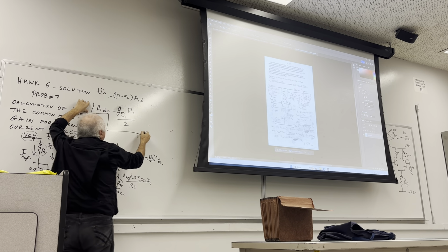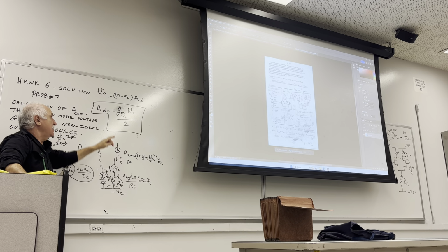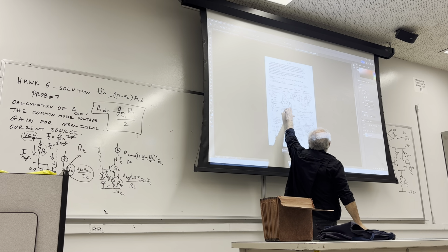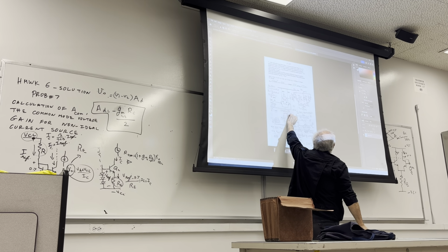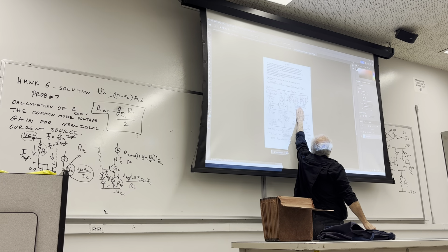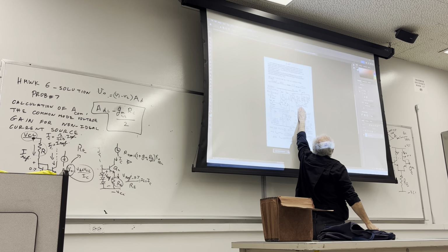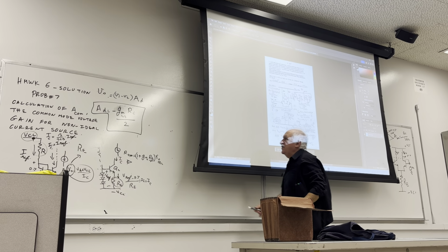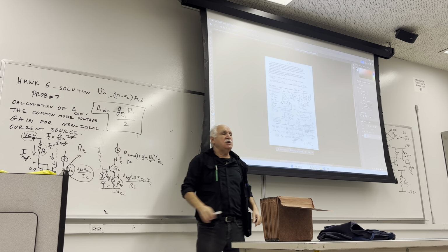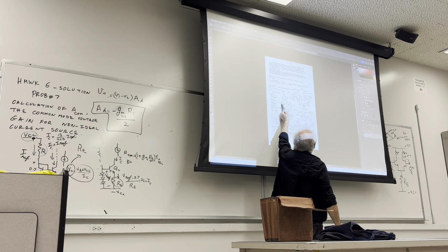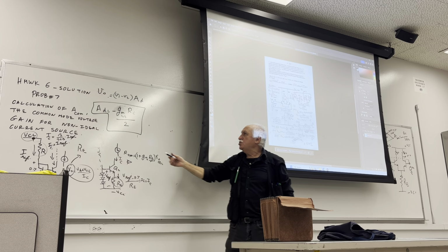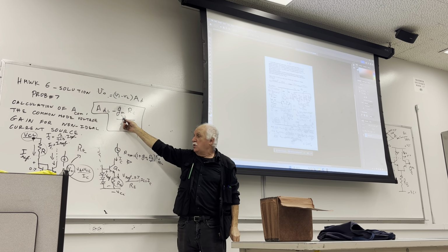So bear in mind that is your differential gain. It's the GM of this transistor which I showed you before in the idealized case. In other words, with this open circuit, infinity. Easily, I showed you that the output voltage is V1 minus V2 multiplied by that quantity, where GM is the transconductance of these two transistors, the amplifier transistors. Now, the ratio of this guy, 2.